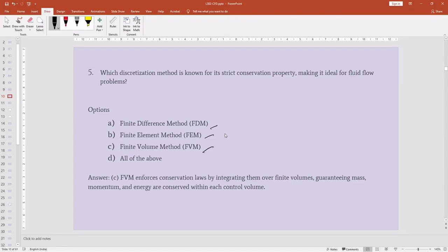If you have watched the videos, you have seen that we start with the vector equation, then convert it using the divergence equation, then take the integral form. So any finite volume method can only be done through integrating our governing equation. Integration is the conservation itself.